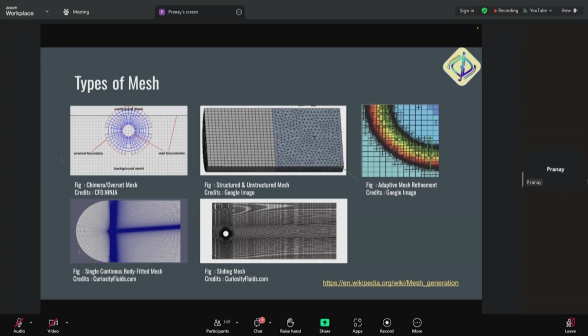There are particular regions of interest wherein flow characteristics need to be highly resolved in that area, like shocks, like combustion, like droplet dynamics, etc. So in that region, we would prefer having a very fine resolution to account for every physics involved in that area. So that's why we prefer adaptive mesh refinement, which is AMR. Once again, it all depends on the physics, gradients, etc.